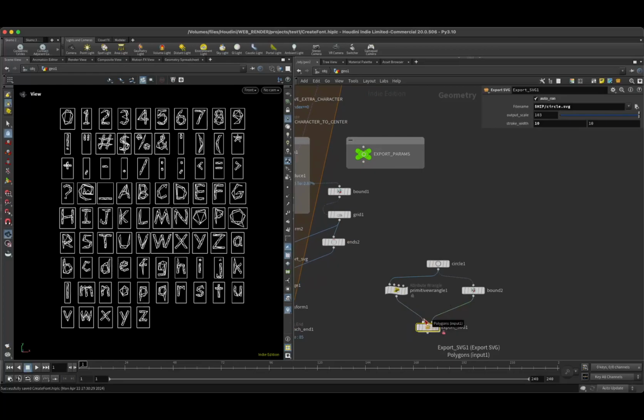So there's two inputs. First one is polygons. Second one is bounds. So I should mention, in the Intagma's video, the bounds were being calculated dynamically based on the size of the geometry. And that wasn't really working for me because I want to have a fixed height for my font. And so I changed this a little bit to accept an explicit bounds object.